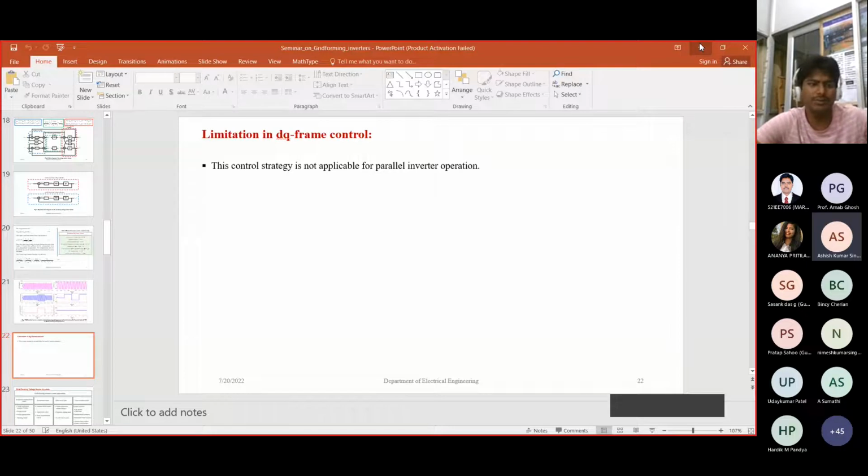First, I have taken a new model. One by one, I will take each component from the library. This is the list of components required: DC voltage source, universal bridge, three-phase VI measurement, three-phase series RLC branch, three-phase series RLC load, and three-phase breaker.